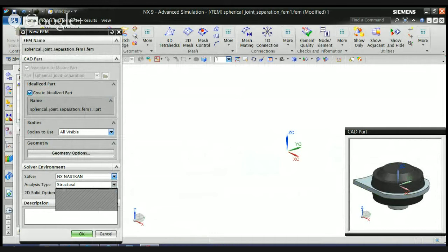Since this is a symmetrical component which is similar in the 360 angle, I'm taking only one particular phase in the 360 angle. From that phase, I'm taking the result. I'm considering the result of the cylindrical wave. So I'm taking this as axisymmetric, okay, and for the axis, make sure which axis you are taking. So I'm taking the ZX axis.